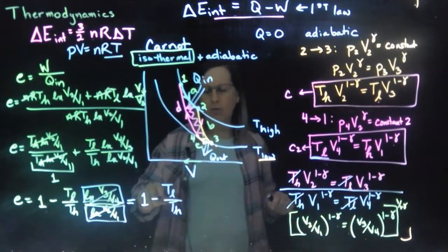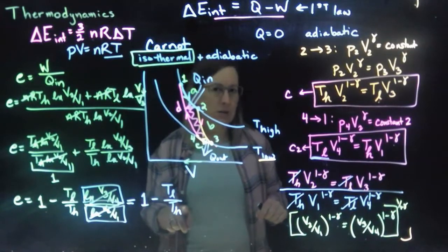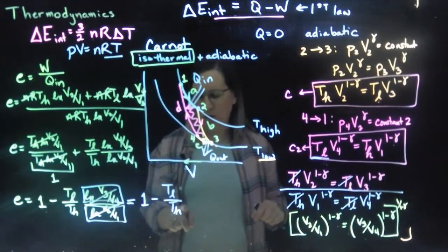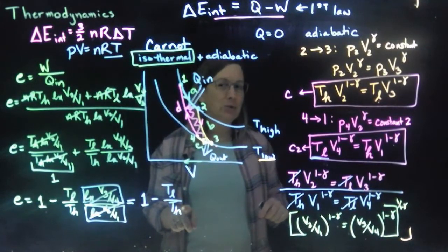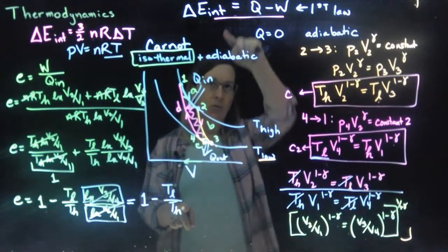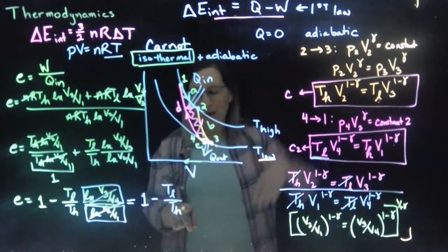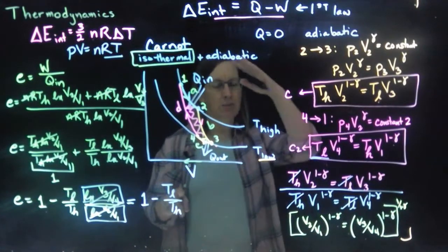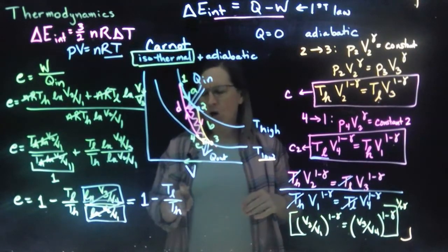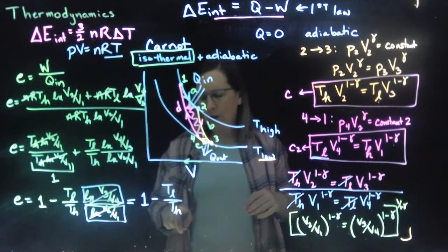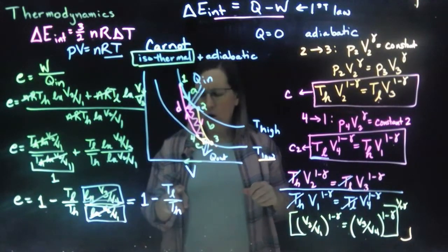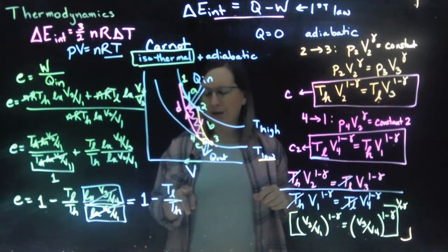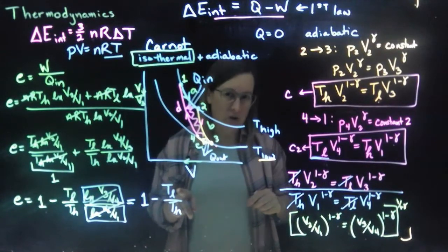What we're looking for is the high temperature side of this equation. We want the high temperature to be really high, not close together. We want a curve that's way up here so I can have a much bigger area. And we want the low temperature side to be as low as possible. So when power plants and such are looking to exhaust, they tend to look for cold exhaust places.